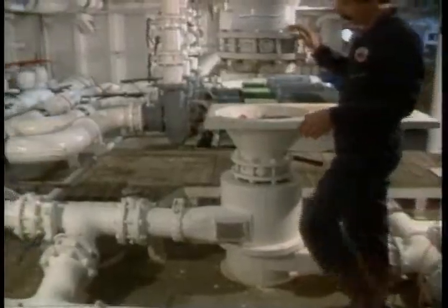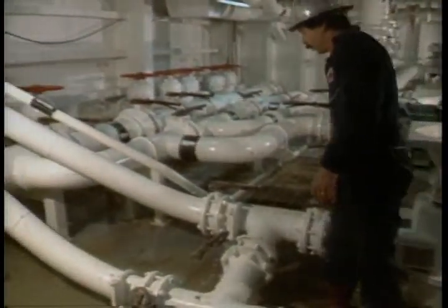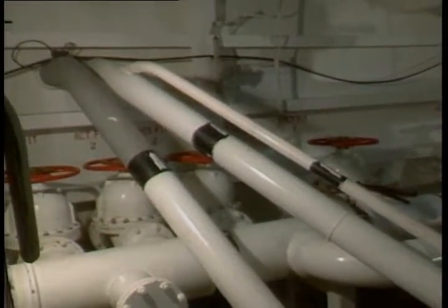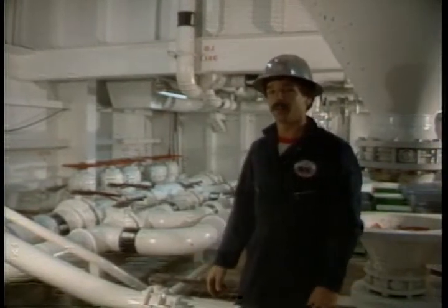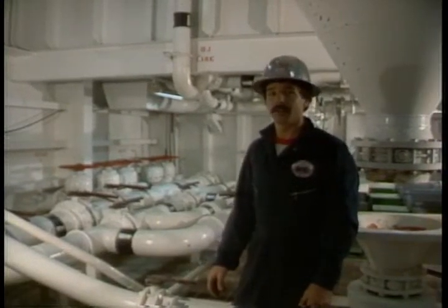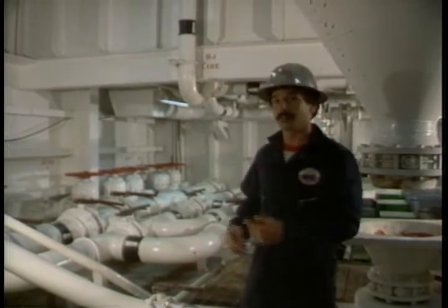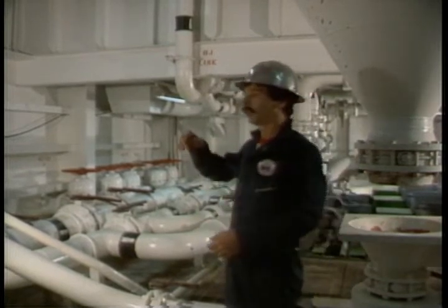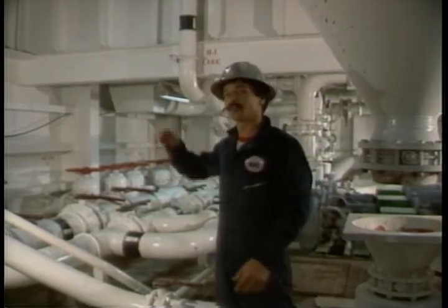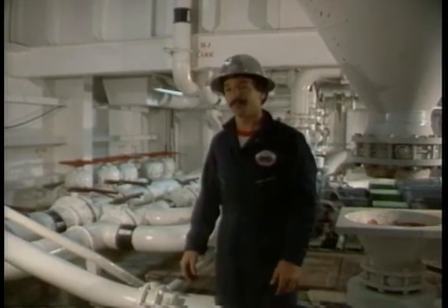I can add my weight material here, and then when it's discharged, it goes through these valves, which are open, goes through the bulkhead, which goes into the pit room. Once I have it into the pit room, it's just a matter of opening up a discharge valve back into my kill pit, which circulates the mud. It's sucked from the kill pit. It's being treated with weight, which will increase the weight, and it's being discharged back into the kill pit.